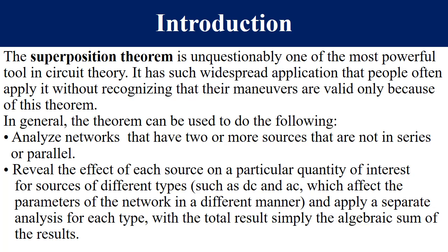In analyzing such networks, superposition theorem enables the effect of each voltage or current source to be analyzed independently, with the total result being the algebraic sum of the effect of each source, so that you find the effect of the whole circuit. So it is very, very important, and you'll be able to use it before the end of this video presentation.